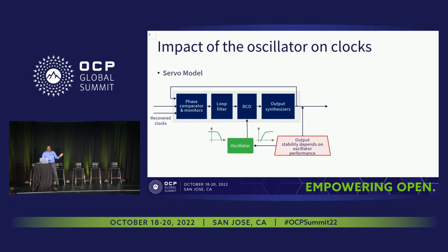So if you look at the impact of the oscillator, we were talking about the oscillator and what is the requirement of the oscillator. It's mainly, if you see, the generic block diagram of an oscillator of comparing the output phase. When the system comes up, whatever is in the oscillator will be reflected on the output, and then the output gets compared with a nominal frequency that comes from the network, and then this phase comparator will drive the DCO to get this nominal at the output.